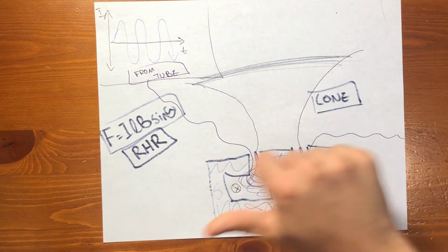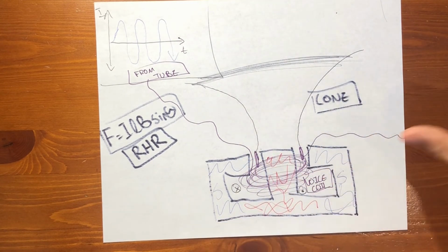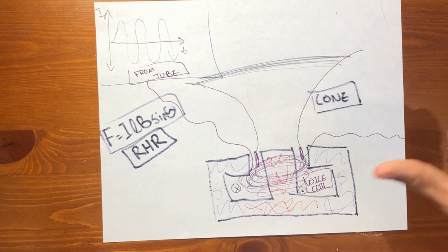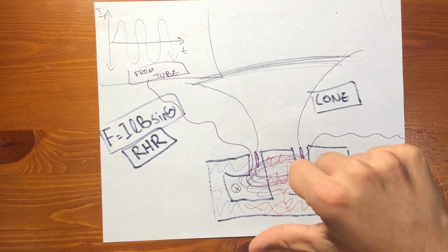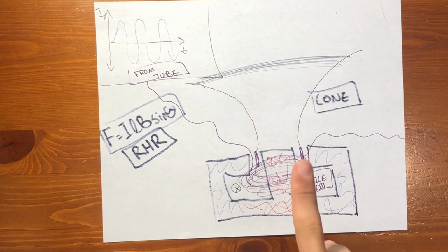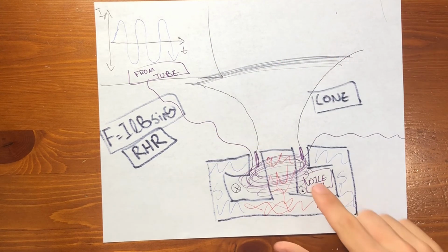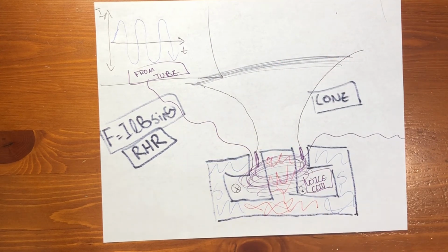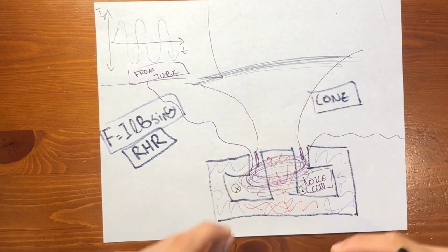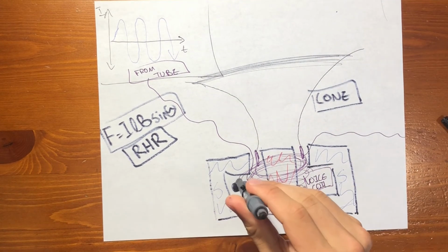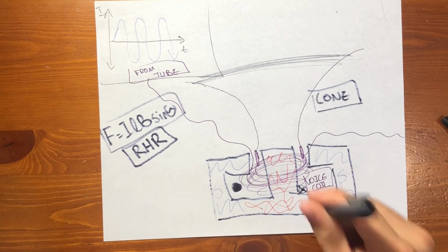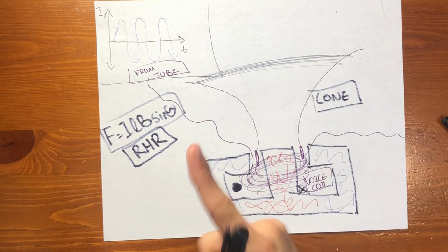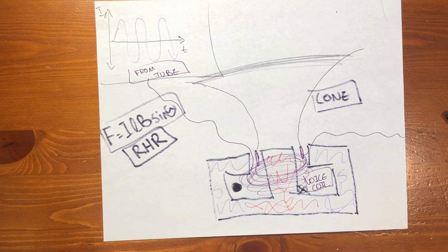All right, we know that our magnetic field lines go from north to south. So magnetic field goes that way. We know that the current goes downwards. Therefore, our speaker cone will be pushed forward. Same thing on the other side. As the current switches the direction in which it is flowing, the opposite effect will happen. It will switch. It'll be coming out over here and going in over there. It'll be going like that. As a result of this, the speaker cone will move the other direction.